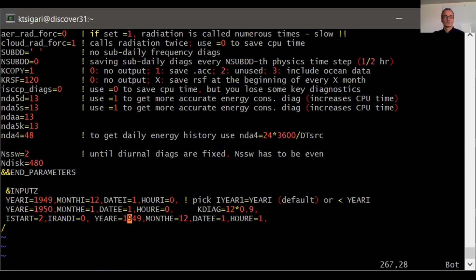So if you overwrite something that you put previously in the run deck with something different, the last statement that you put in will take effect. Like if you have k copy equal to 1, and you add a line after it that says k copy equals 2, it will use k copy equals 2. Yes, that also goes with input files, but you'd better not do this because it may have some weird consequences.